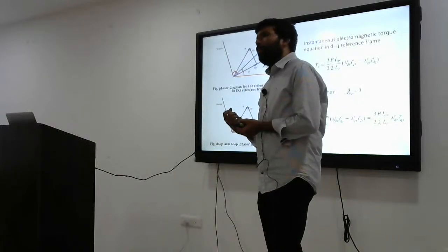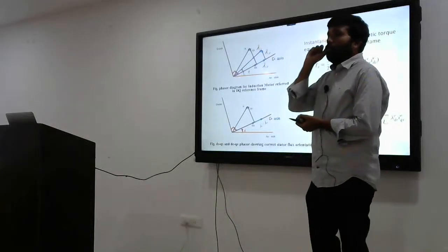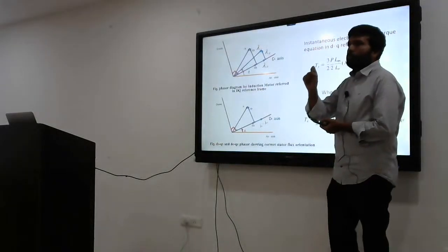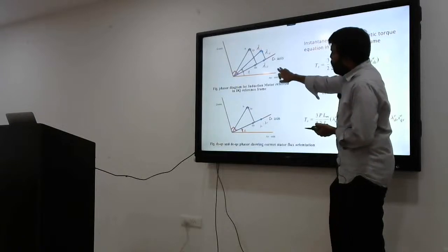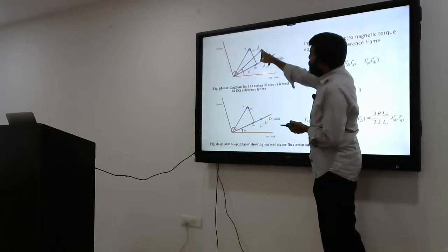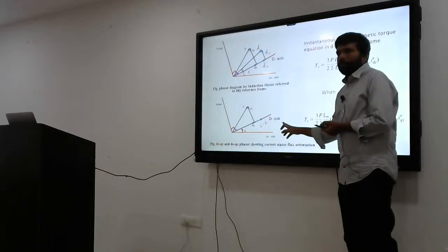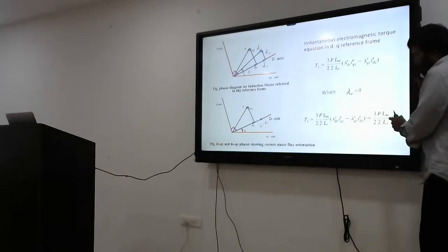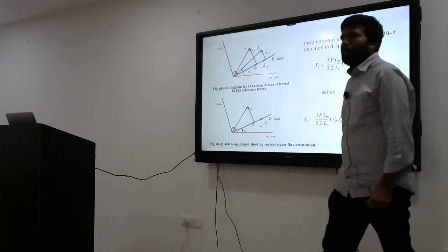Nowadays, there are so many optimization methods they are adopting to identify the rotor flux position with less parameter effect. Okay? So once the D axis is in phase with lambda R, the advantage is that the lambda QR effect is 0. If lambda QR is 0, finally how many variables are there? 2. Still it is in nonlinear mode.